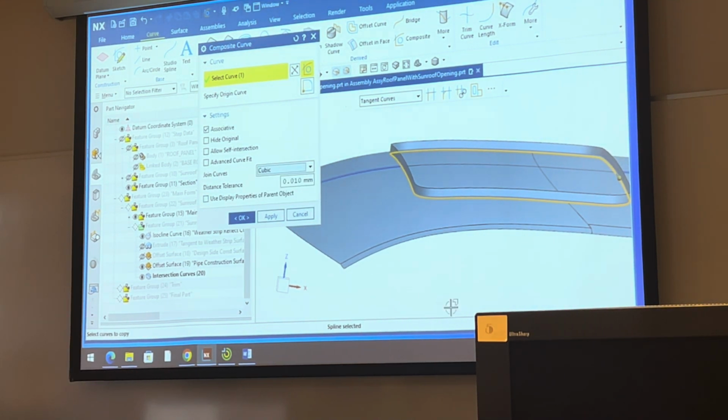So we're gonna do a cubic, which again means a third degree polynomial. We're gonna change the tolerance that helps smooth it out a little bit more. Instead of 0.01, it's gonna be 0.1. I have a point there. Yeah, a lot of times I end up with 2 points, but 0.1.